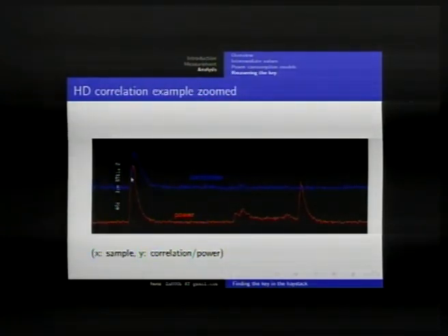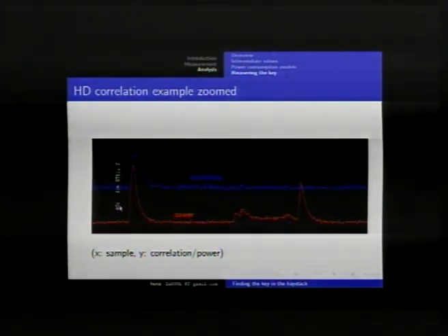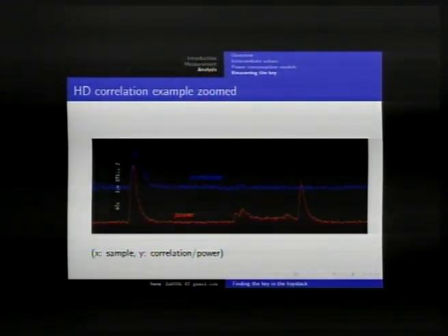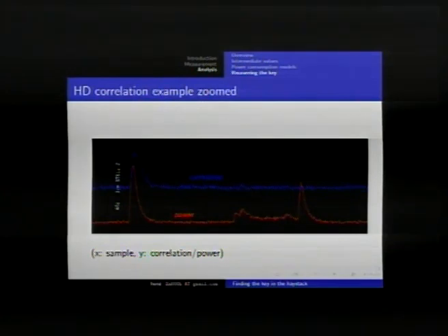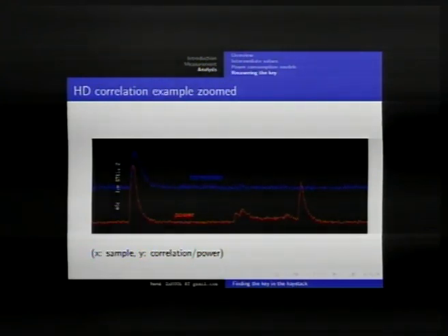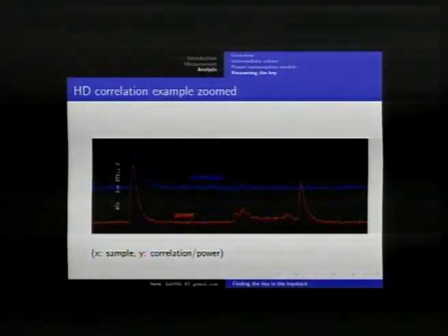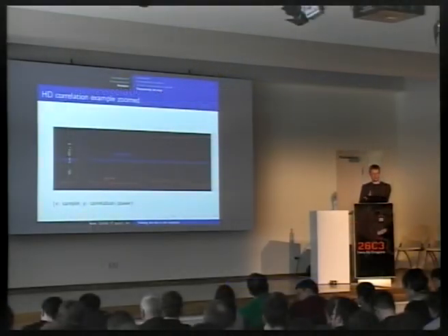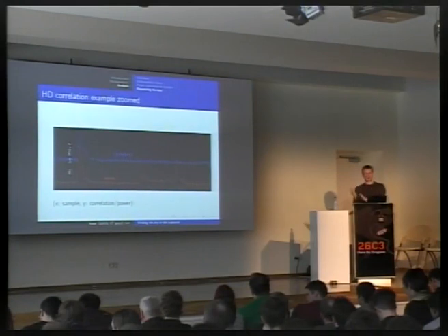To write the instructions here, you of course need some kind of reference. I did this by adding a trigger output to the AES encryption routine, so it will switch one output to 1 each time the AES encryption starts, and I can count the cycles through the assembler instructions, and then I know exactly at what time in the power traces or in the correlation trace which instruction is executed.